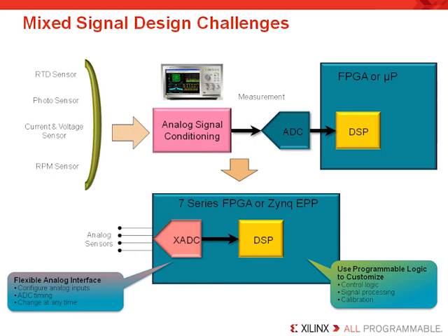Now, there is often the need to calibrate, i.e. remove the offset and the gain errors in the analog signal processing chain, and perhaps remove nonlinearity associated with the sensor itself. While many of these functions are commonly implemented in the analog signal processing chain or sometimes in a microcontroller, they can be more efficiently implemented with the digital signal processing capabilities of an FPGA. This is especially true for high channel counts and where complex filtering is required in a system.